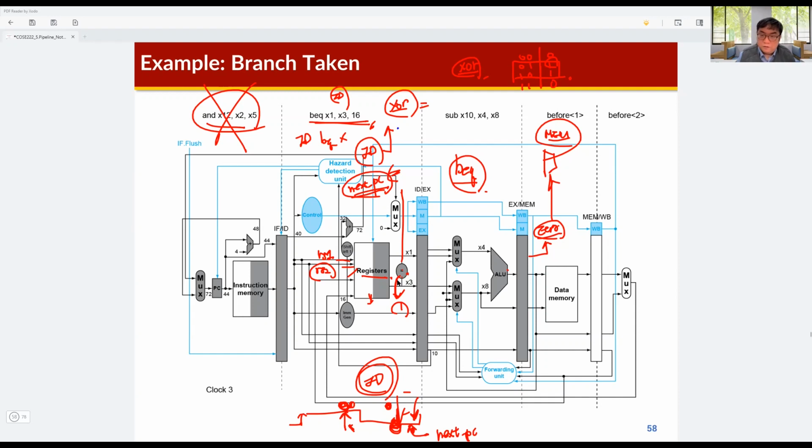In the previous class I explained how to detect different bits in the two data: we can use the exclusive OR. Because this hardware is very simple, we can add it after the register file, and make the condition of the branch resolved earlier.